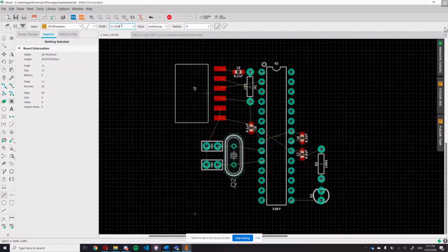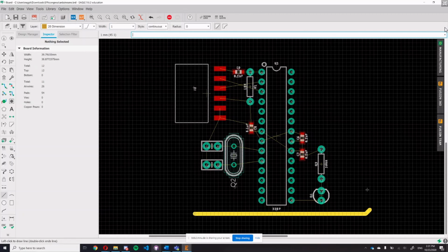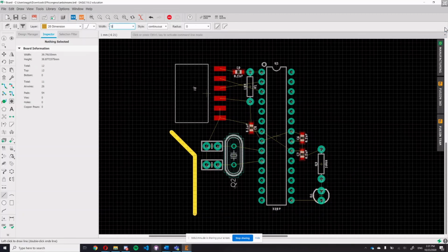So you set the width to 0, because the tools which are milling the board, like the CNC mill, are not precise because the drill bit has some width, but you want to have a perfect model of where it should be drawn. So you don't want a millimeter thick outline, because then you don't know what to expect. So normally it's put at 0.